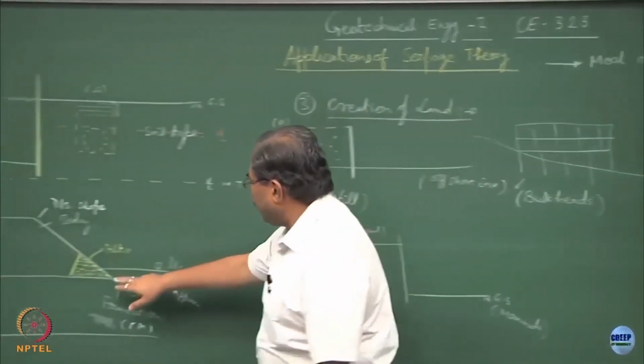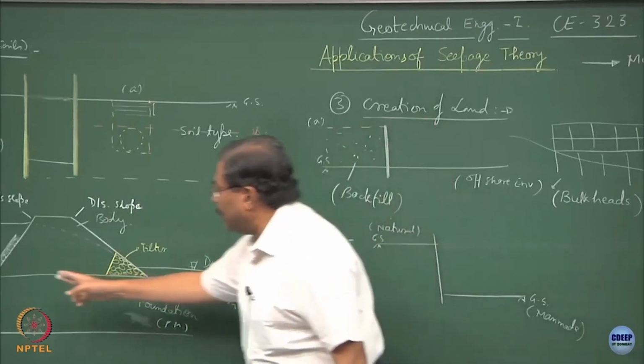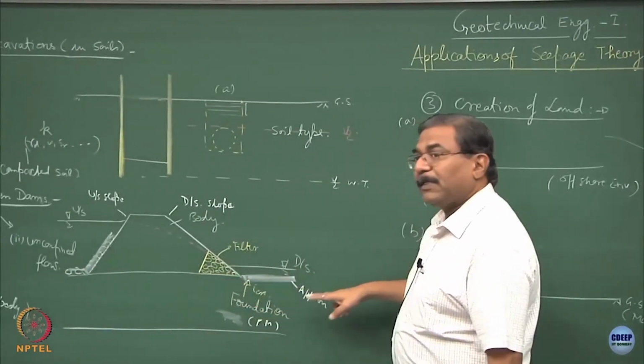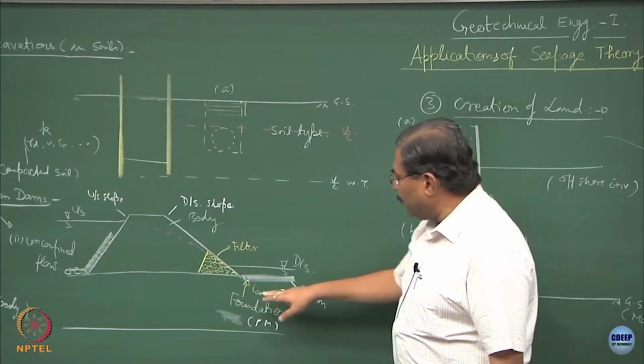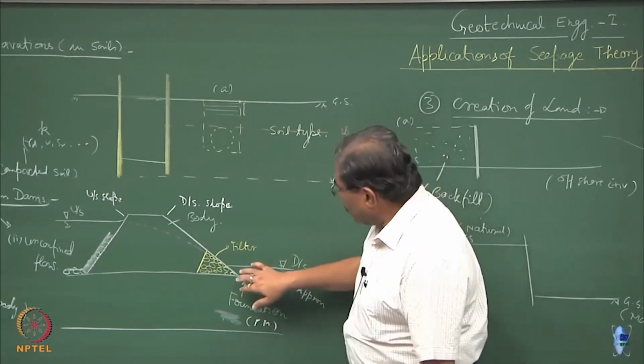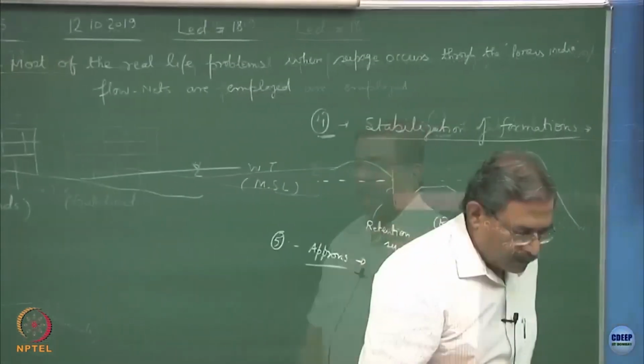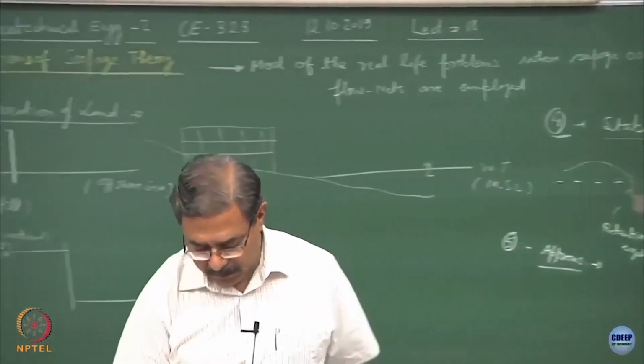So, if I create an apron over here, very soon you will learn what I have done is I have elongated the seepage length and hence the hydraulic gradients are going to be less, fine. So, this is also you can study under the same head, good. What is apron exactly? Good.